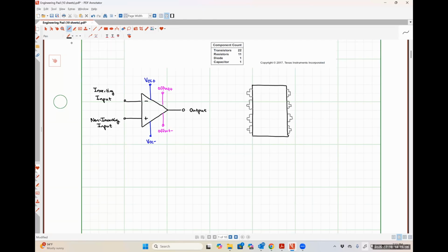Usually, you will see on one side of the package either an indentation like this that's kind of a semicircle, or you might see a small circular indentation like so. This is what's telling you where pin 1 is located on the actual chip.